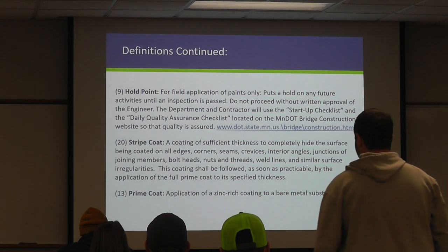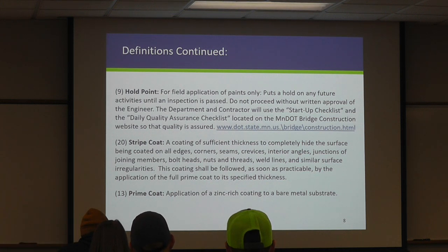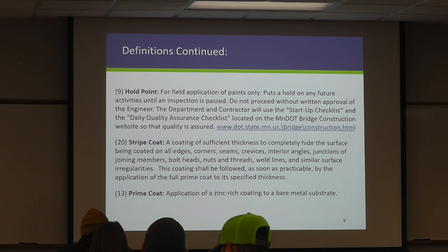We'll discuss hold points, and hold points are basically points during your inspection process that enable you, the inspector, to take a pause from the contractor. Time is money. Everybody wants to just sail right along, and these hold points were put in as a way for you to check certain processes before the next thing gets covered up.